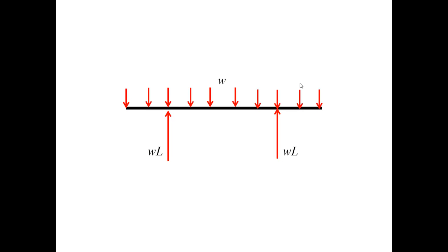In this beam, we certainly need to make a cut on the left between the left tip and the roller. Then we need to make two more cuts, one in the middle of the beam and another on the right side of the beam. Nevertheless, because the beam is symmetric, we can get away with only two cuts, one on the left and another in the middle. The cut on the right will give us information that can be reconstructed from the cut on the left.